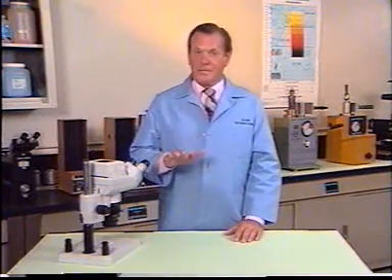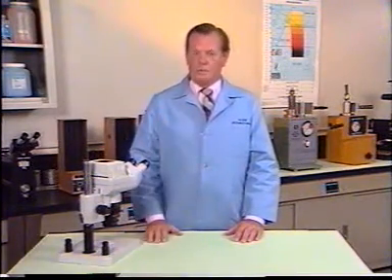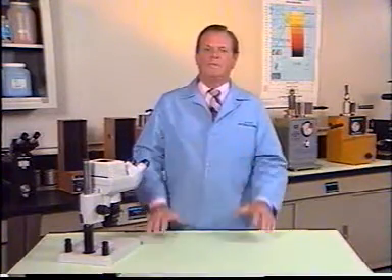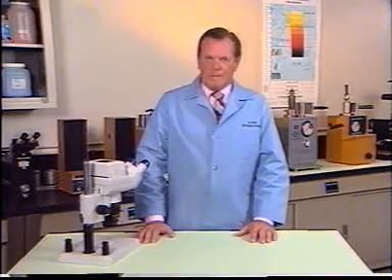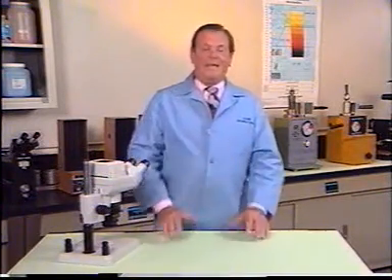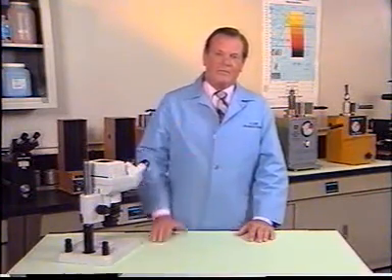And this is considered failure, even though the part, machine, or equipment may continue to operate with what essentially is a faulty component. Though fracture, wear, corrosion, and distortion are generally considered the major types of failure, it must not be assumed that each acts independently of the others. Indeed, one of the challenges in the field of failure analysis is to recognize the wide variety of combinations and interactions of fracture, wear, corrosion, and distortion.